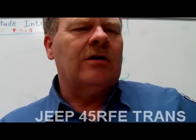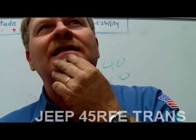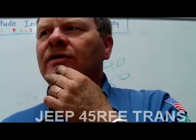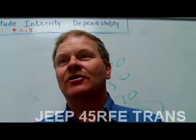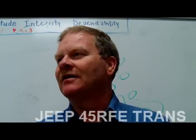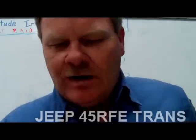Some of these Japanese cars, Volvos or something, Joey Hendrick out there in Russell, Kansas does this all the time. All he does is programming. He said some of these Volvos will take 8 hours to reprogram, to reflash. It's incredible. You have a special battery charger with no ripples. I've got one of those. You hook it up and you just have to be patient. Just let it sit there, it's going to take all day long. You better hope you don't lose power, because it wipes everything out.